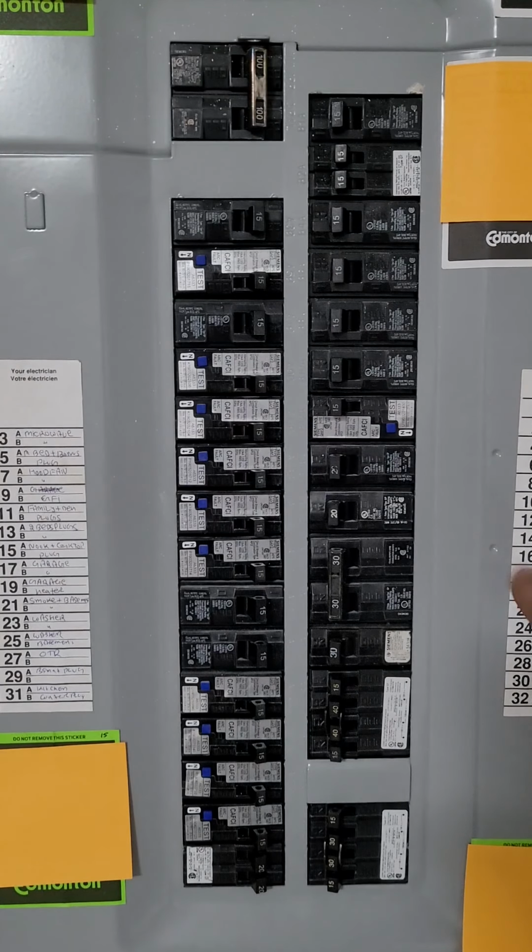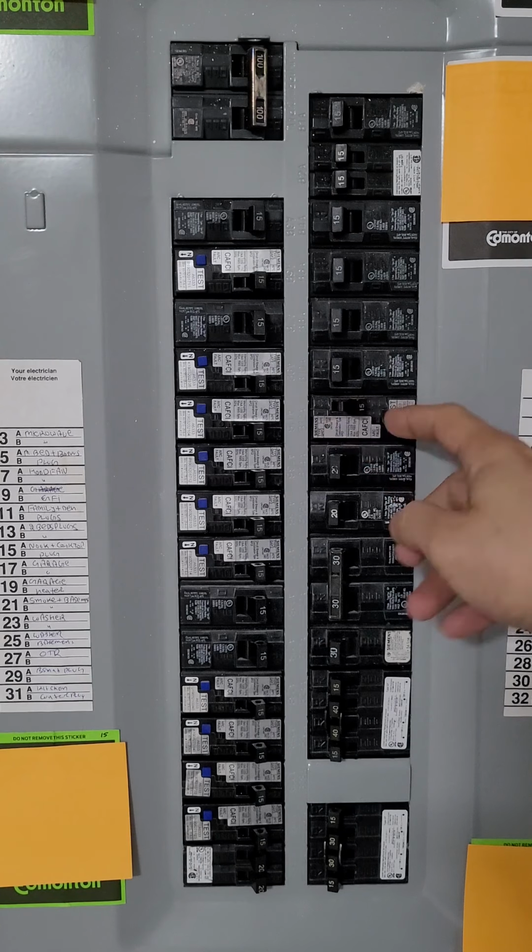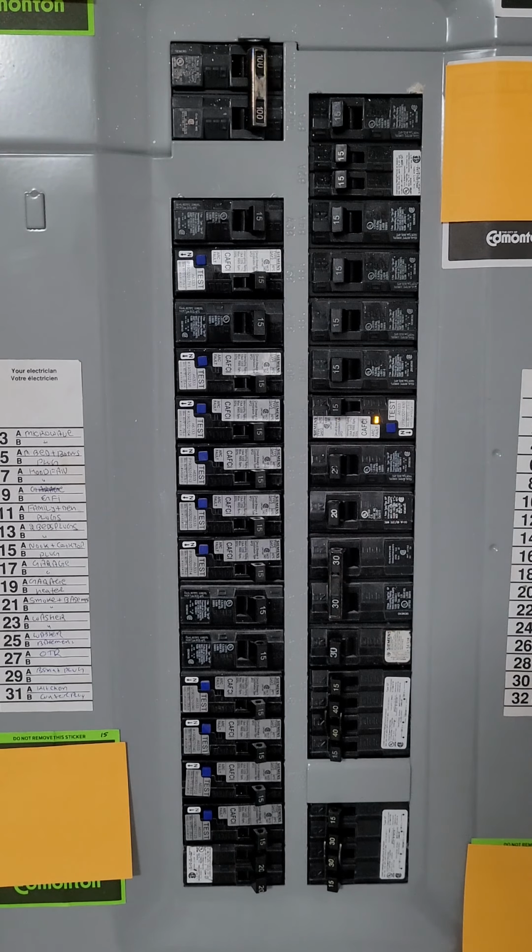A second type of breaker is arc fault breakers. So this one is with a test button and a blue color. So if I press this, it trips off the breaker. What this does is it protects against fire caused by arcing faults. That means a sudden rise in power consumption or loose wiring, and it trips very easily with very slight overload